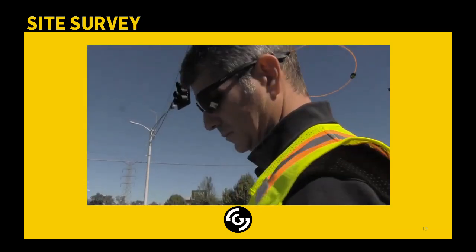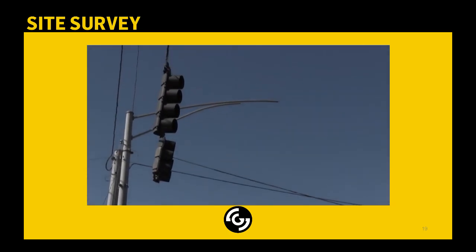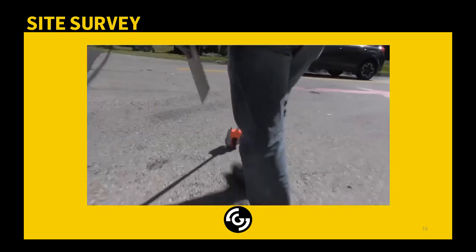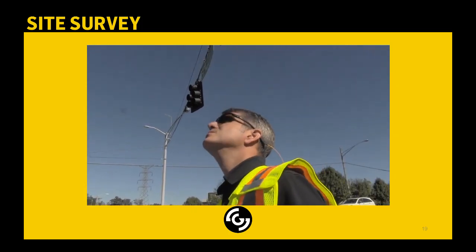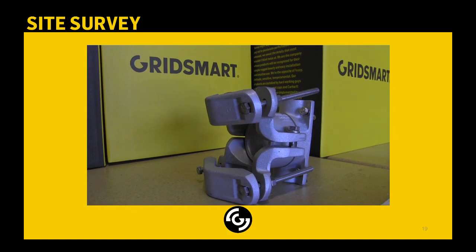Tell us where you intend to mount the camera. How high off the ground will it be when installed? And the estimated cable run from the camera to the cabinet. Be sure to include the pole height, arm, and pull boxes in your calculations. This survey also allows you to enter information about the type of mounting pole and hardware you will use or need to complete the installation.